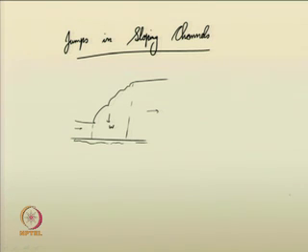How are jumps formed in sloping channels, or why? You know that in sloping channels, especially if it is a supercritical flow, if there is any change in the bed slope downstream, whether it becomes horizontal or adverse, whatever it be, due to this change in slope hydraulic jumps may be formed.